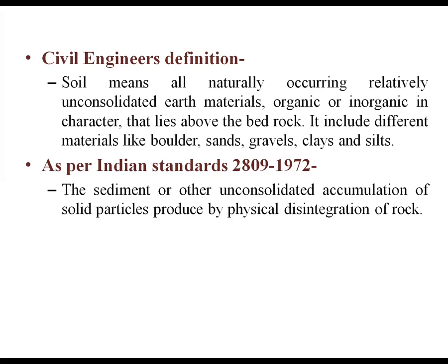Okay, from the civil engineering point of view, soil means all naturally occurring, relatively unconsolidated earth material, organic or inorganic in character, that lies above the bedrock. It includes different materials like boulder, sand, gravel, clay, and silt.